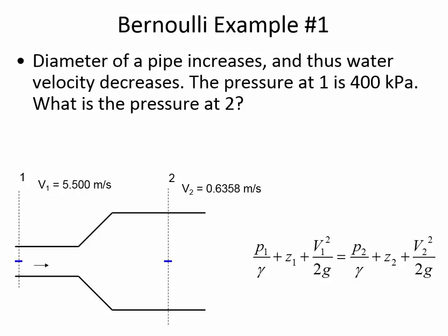Are there other questions about this? Would the velocity in that situation, at the center of the pipe where the neck is, be greater? So if you're talking about the center line, here is one location and here's another, yes, the velocity is definitely higher here because the diameter decreases and the reduced cross-sectional area forces the velocity up. And that's the reason why there's a change of pressure.